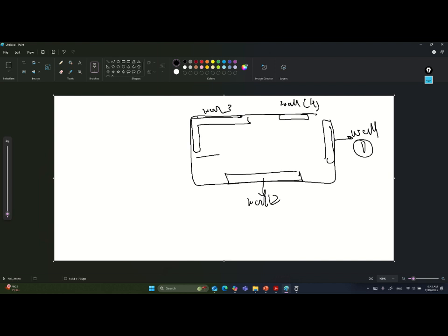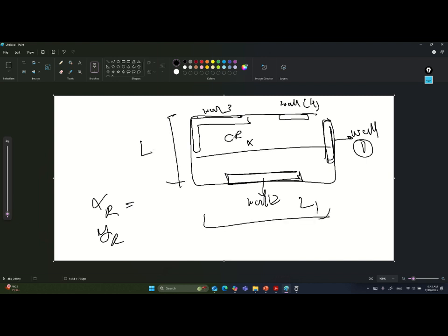So you will calculate the x for rigidity and the y rigidity, depending on each wall, and after getting them it will be something like here, that is the center of rigidity. I have L1 and L2, so I will consider the center. If he doesn't give me the center of mass, then I will consider it in the middle.